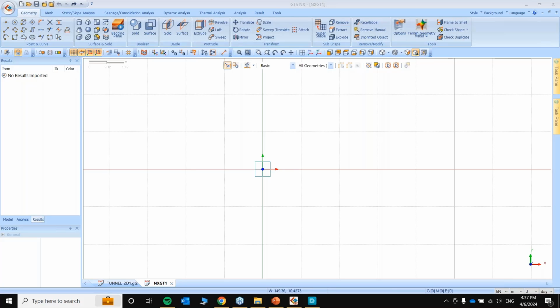Then I have another question: how to address variation in soil strata along the length of TBM in a line model. To address the variation in soil strata, you can model it by modeling different chainages in 2D, or if your strata have extremely large variations in geomechanical properties, you need to go for a 3D model. So here we have the bedding plane wizard, where you can import your borehole data directly and apply the soil layers in there. That will be also covered in the upcoming sessions.